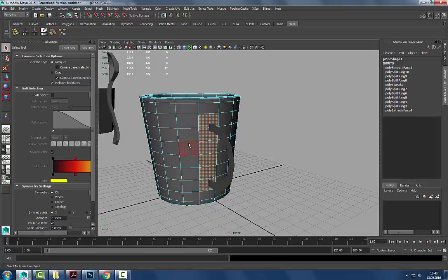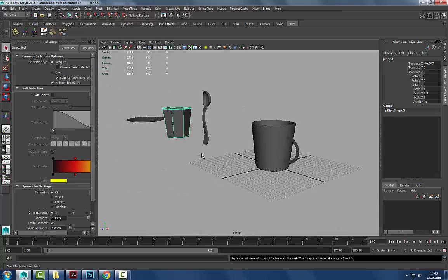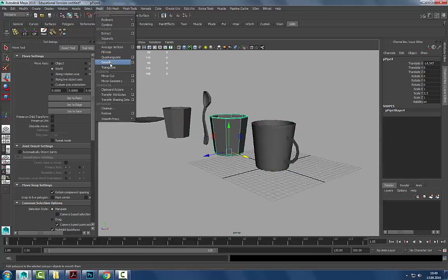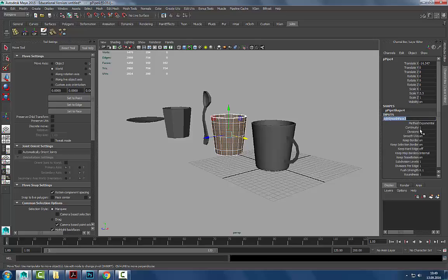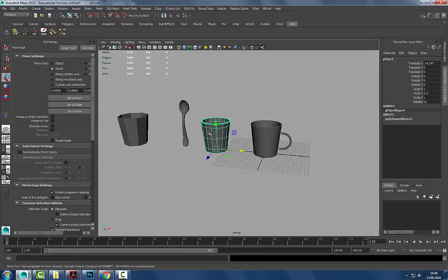What I mean is I'm committing to the shape. I'm working simply, I'm subdividing, but at some point we need more details. So I go, can I smooth it now? Okay, I'm committing to the shape. I'm smoothing it in division 1, which means it's going to quadruple the poly count. Gives me more vertices to work with, or more polys to work with.